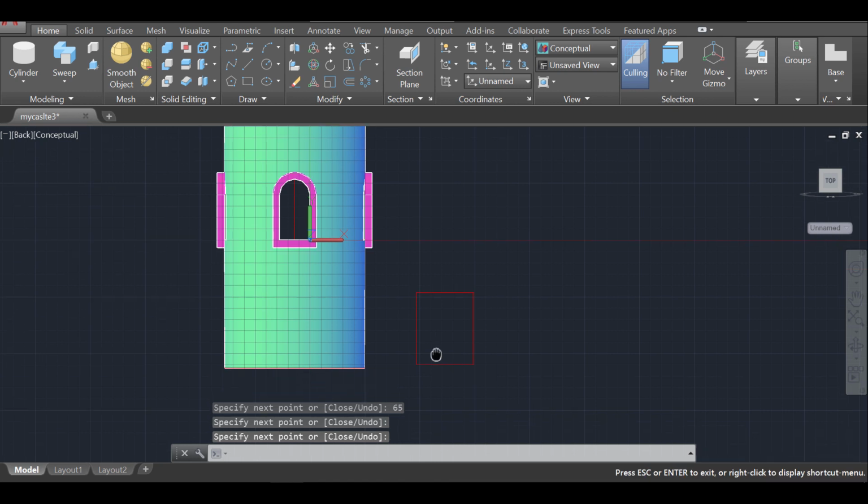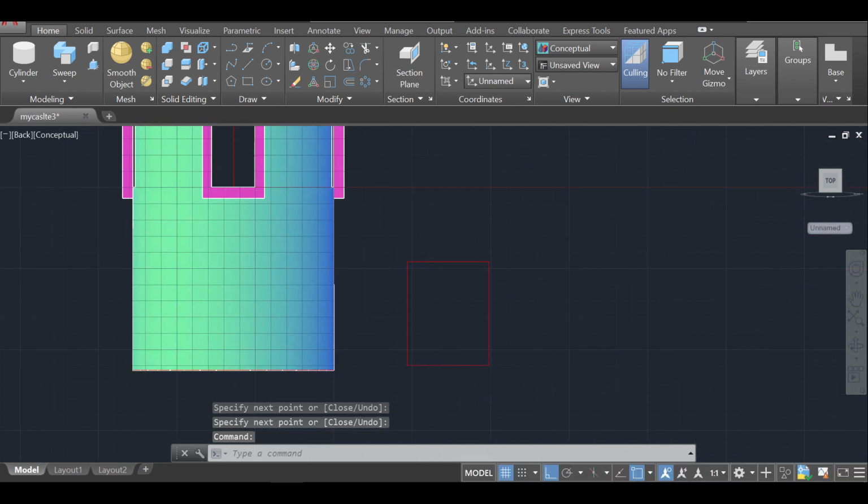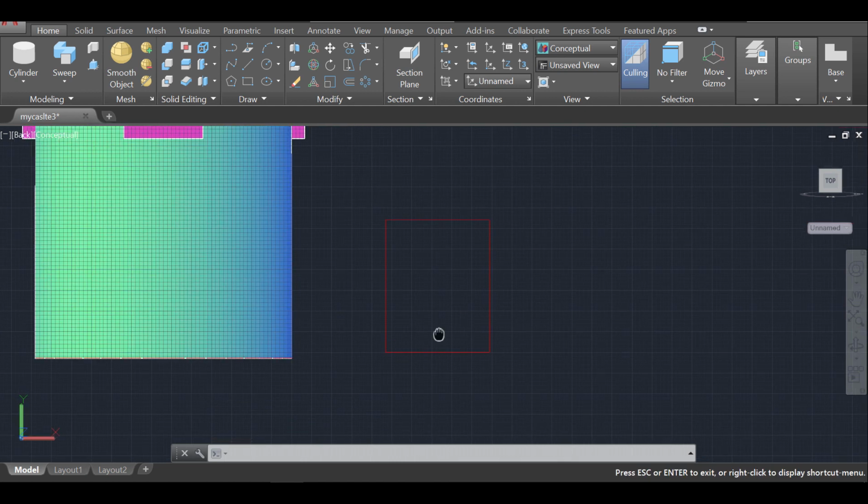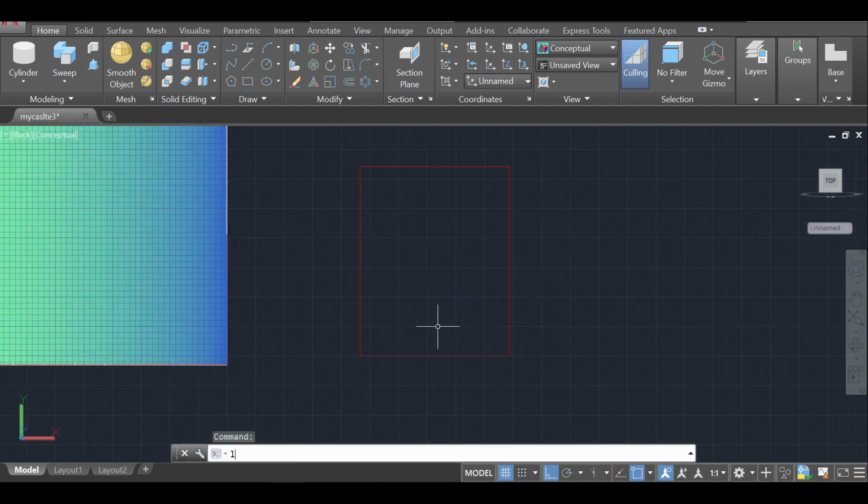I want my door to have a frame too, like the windows. So what I'm gonna do is go ahead and create that frame. It's gonna be 8 units thick, so 8, enter. And there are different ways for you to do this. I'm just doing the way that is kind of easier for me. I'm pressing the space bar a few times, so it's easier to get in and out from the line command.